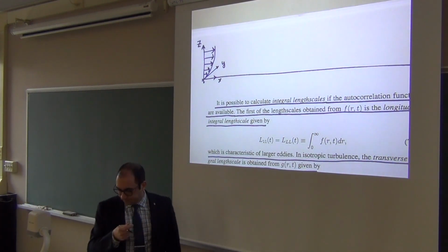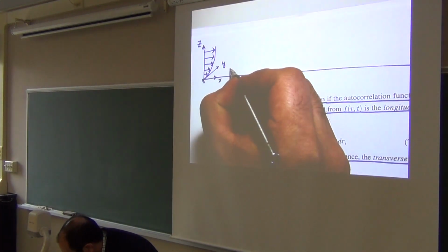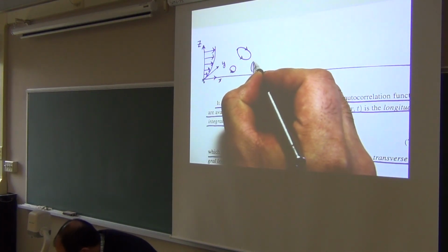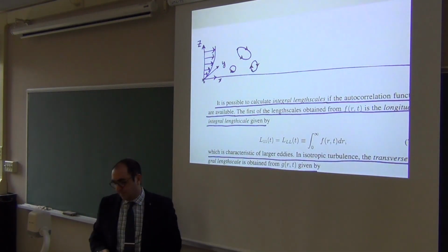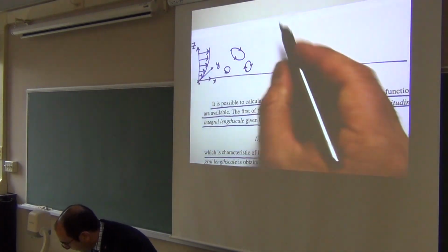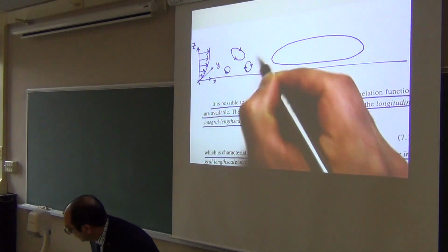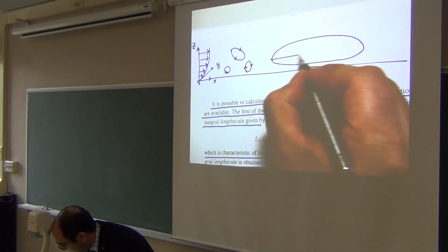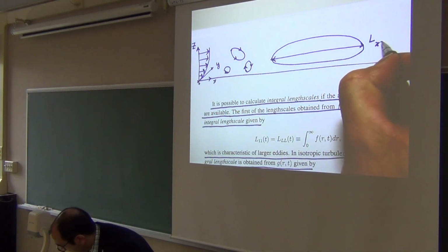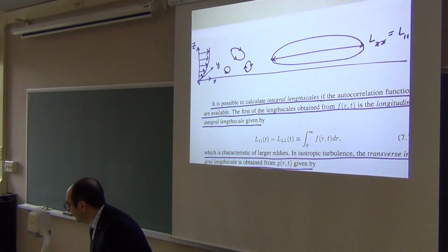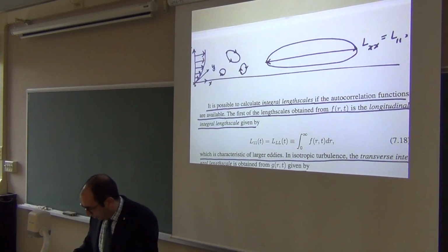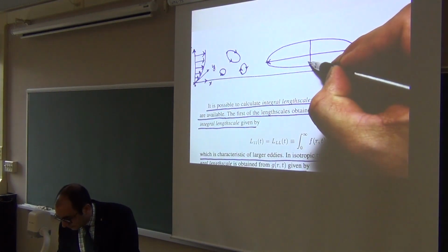You want to characterize, I mean, of course, a lot of eddies would form, right, of all different sizes. There could be many eddies, but statistically speaking, you can describe all of these eddies with one longitudinal size, like LXX or L11, if you want. You can characterize all of these eddies by two transverse sizes.